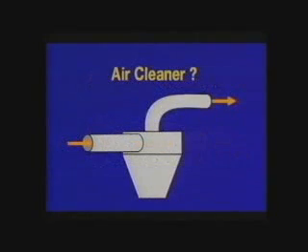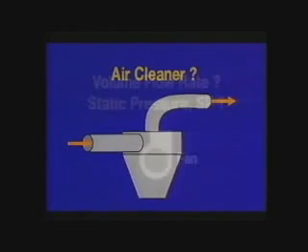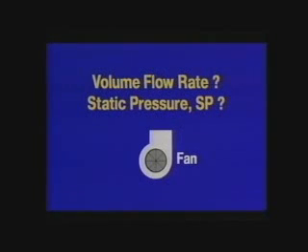Is an air cleaner required? The answer to this question must be obtained from the local air pollution authority that will issue a permit. How large should the fan be? Fans are chosen to match the requirements of the exhaust ventilation system. The fan must move the correct volume of air against the resistance to airflow caused by friction and turbulence in the system. The designer will estimate the static pressure required.